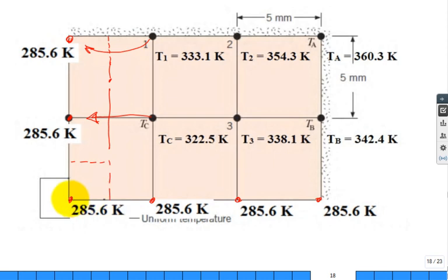What gets to this node? Well, really you don't have any conduction other than from the sides, but that's already the surfaces. I don't worry about this one to that one. They're the same temperature, so it's just coming from the interior. So then this is a flow, and this is a flow, and this is a flow. Remember, this is half an area.